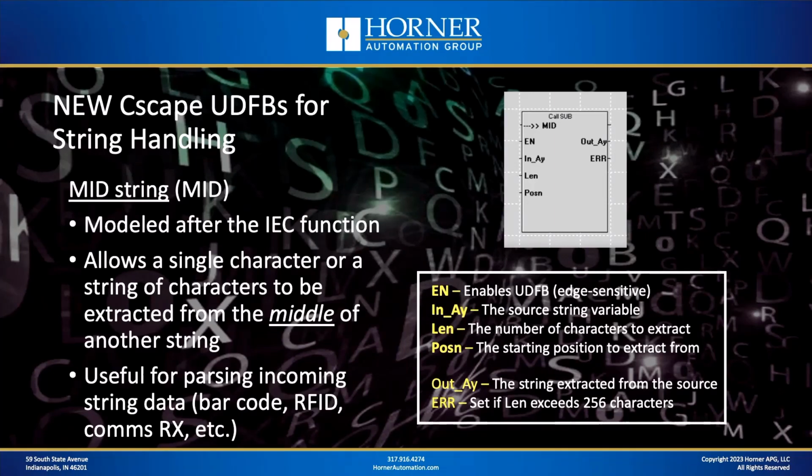So let's start with one called midstring, which is just represented as mid on the UDFB. So what does the midstring function do? Well, this function, along with the others that we're going to be talking about today, were really modeled after an IEC function that's currently available if you're using the IEC version of Cscape for logic. But a lot of you are really comfortable with variable-based advanced ladder, the American style ladder, and you'd like to have some of that string type capability, but in the variable-based advanced ladder type programming style. So that's really the reason for us developing these user-defined function blocks for you all.